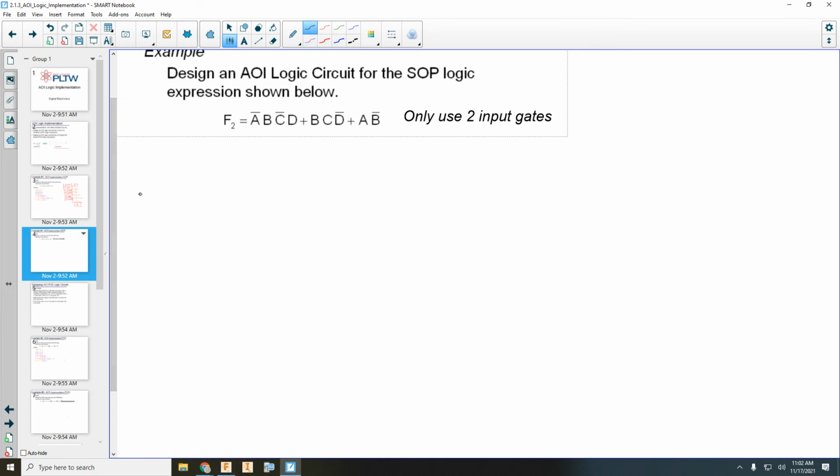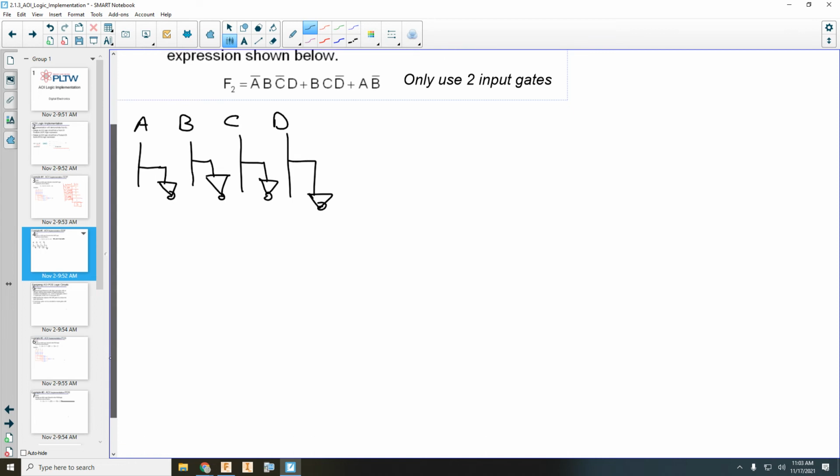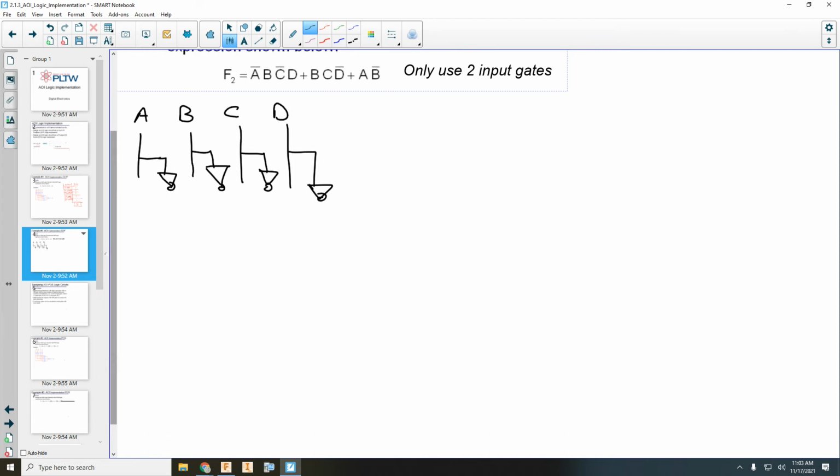So if you notice, sometimes you'll see gates drawn horizontally. What we usually do, it makes it better, is if you have your 4 variables or 3 variables, you line them up vertically, and we do need an inverter for each one of these. So if you sketch your inverters coming in vertically, and then to build your circuit, you can then have your ANDs and ORs going horizontally. And it takes a little bit of planning so you don't end up with a bird's nest.